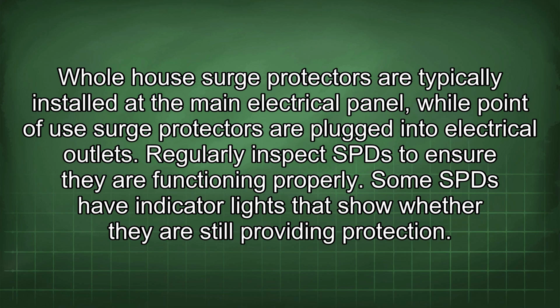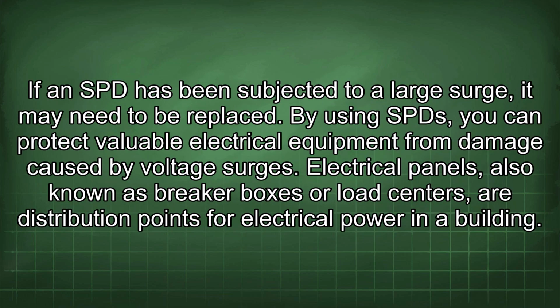Regularly inspect SPDs to ensure they are functioning properly. Some SPDs have indicator lights that show whether they are still providing protection. If an SPD has been subjected to a large surge, it may need to be replaced. By using SPDs, you can protect valuable electrical equipment from damage caused by voltage surges.